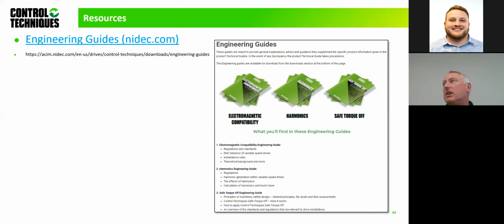So yes, one of the things, if I remember on parallel generators, is that when you synchronize generators in and out, you need to make sure the synchronizer can synchronize that distorted waveform. Again, if it's too distorted, they may have trouble synchronizing the generators in and out. Again, it depends on the synchronizer for bringing that generator in and out.